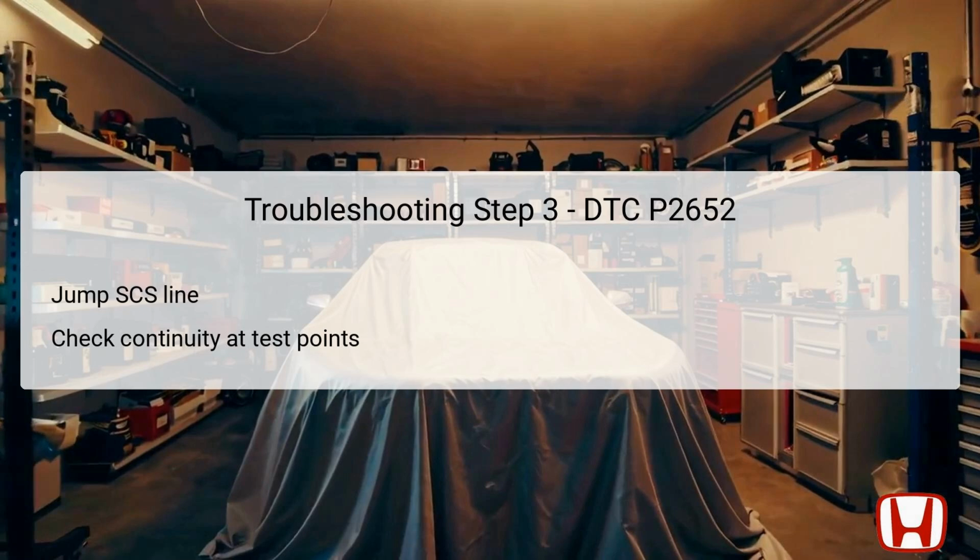safely. In the fourth step of the troubleshooting process, you will assess the actual oil pressure within the VTEC system to ensure proper function. Remove the rocker arm oil pressure switch from the rocker arm oil control valve and attach the appropriate special tools to facilitate measurement.